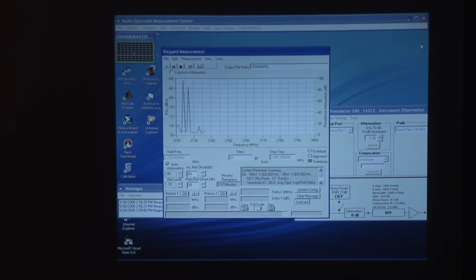So the noise figure of our overall measurement system, in other words, is being determined by the low noise amplifier at the front end. That's optimum, that's what we want. We're still seeing measurement system noise as we work our way across to 2,740 megahertz. This technique may look slow, but it's faster than doing maximum hold mode with peak detection in a spectrum analyzer. And as we've pointed out before, this allows us to get wider dynamic range because we can step the attenuation as we move along. That was another momentary hit from a source that was not the radar.